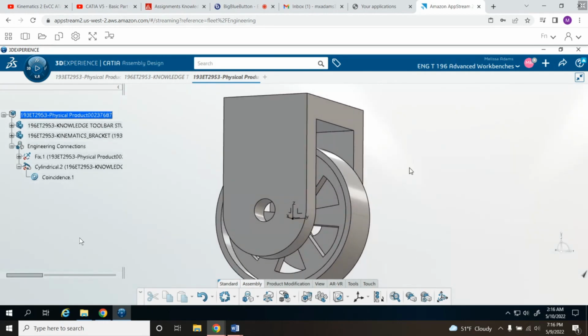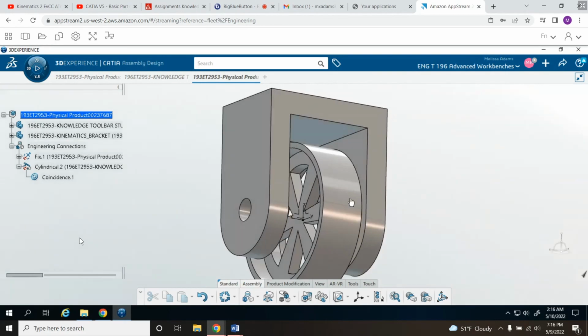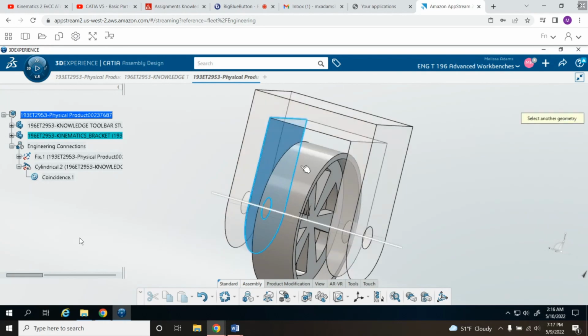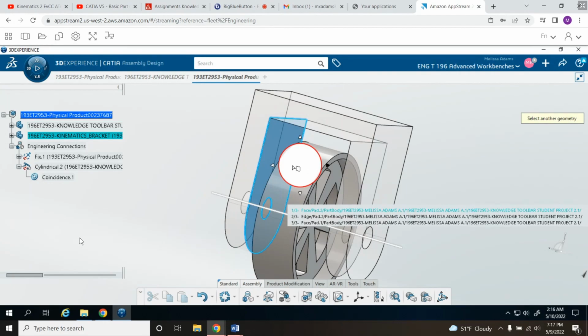Okay, and then we're going to do that offset business, right? Where I control it. Because you'll remember that when I did the kinematic one, it just goes and touches a wall. So if I just click on a face, you'll have a choice to go to offset. And then go pick the other face on the wheel.